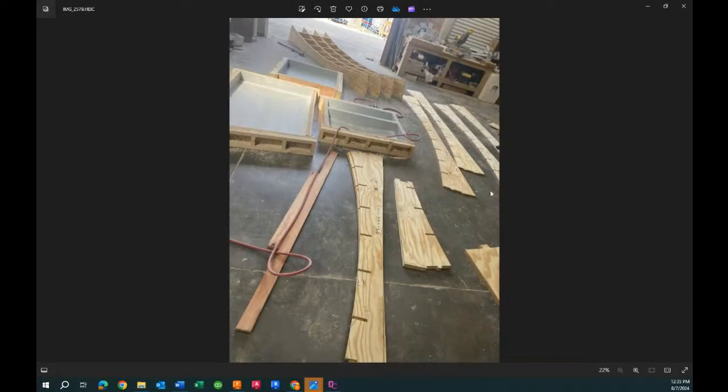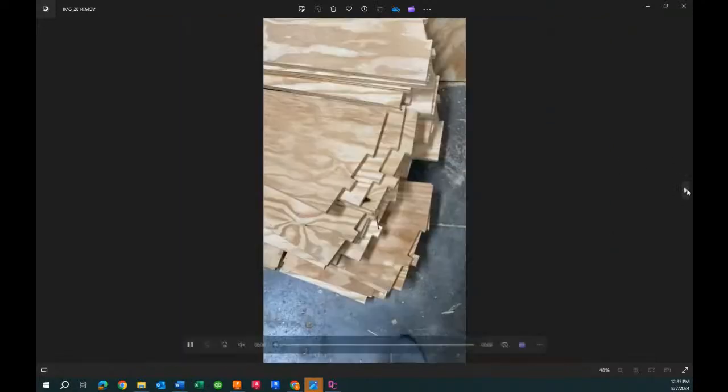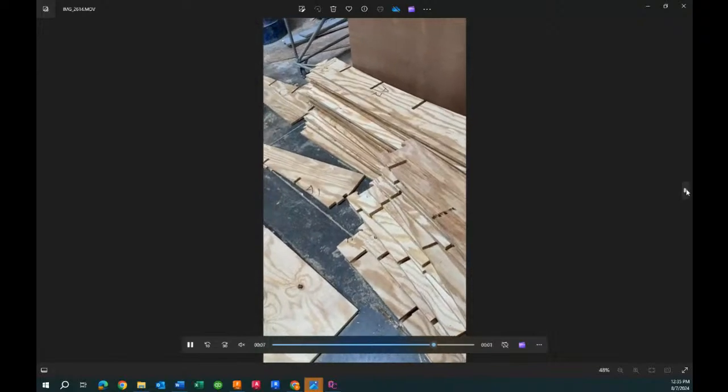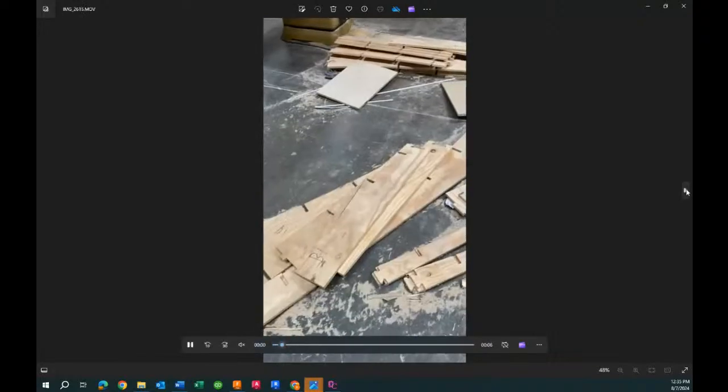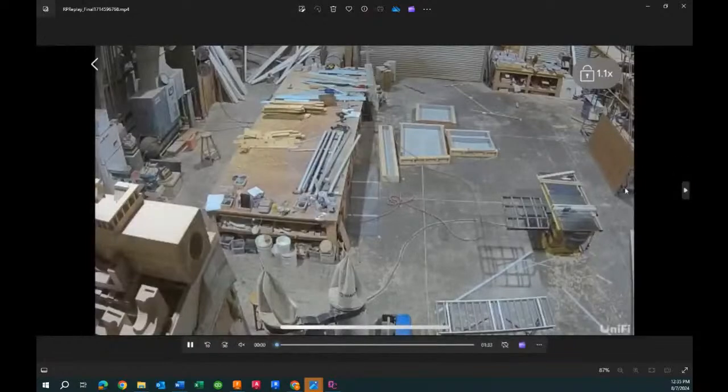We, again, had the dovetail element that's on here. In this particular case, we treated these as a series of forms that we basically created a bulkhead in between each radius element. We did that for one reason, mainly because it allowed your least skilled guy to put these forms together at this point. So these were bulkheads that basically allowed this form to get placed together. Let me show you how that happened.